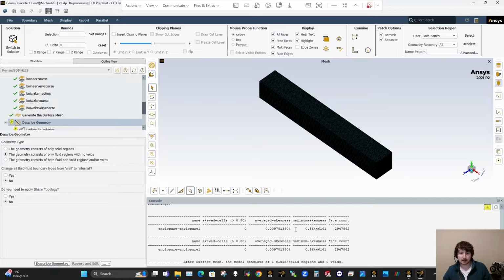Just one thing as well, if that doesn't work for you, you maybe need to go back and look at the BOIs we created and use the facets tool to see if there are any protrusions on the mesh on those BOIs. Check facets and then auto fix on them and mess around with them, because if there are any errors here, they come from them not being clean enough. And you can always shrink wrap them as well if you're having issues.